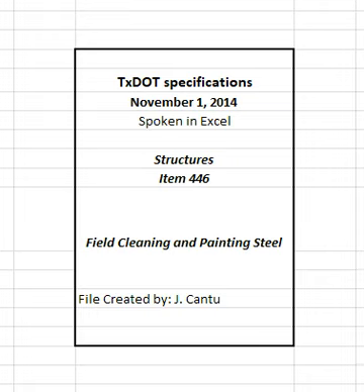All paint systems require water blasting to remove contaminants before any other surface preparation. Both System 1A and 1B require tool cleaning for defective areas of disbonded coating or rust. All other paint systems require abrasive blast cleaning unless otherwise shown on the plans.